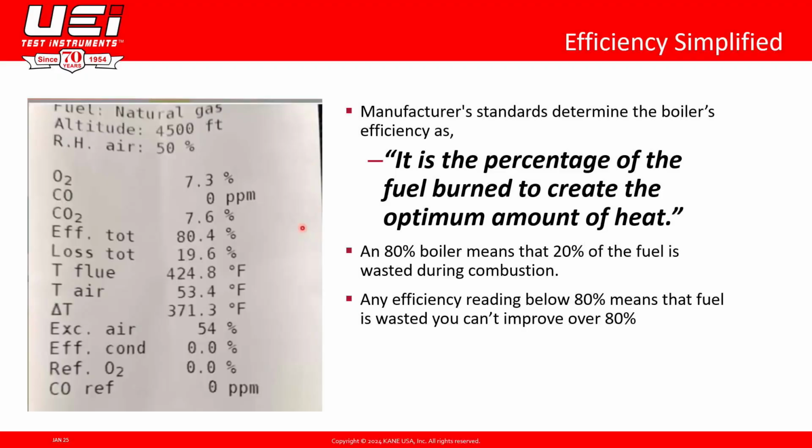We don't want to go chasing that efficiency if it means that we are taking that unit outside of what the manufacturer specs say it can be. Because again, if we wind up having it with too much gas and we wind up with it burning too hot, we could risk cracking a heat exchanger. We could be putting a lot of excess carbon monoxide into a living space.